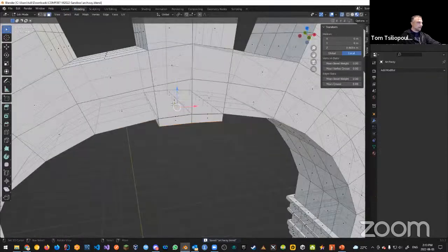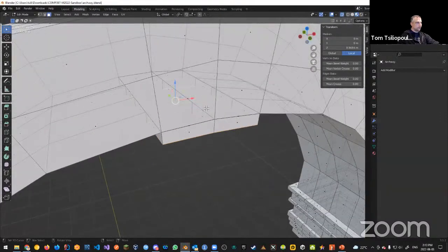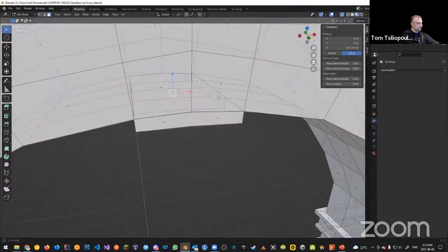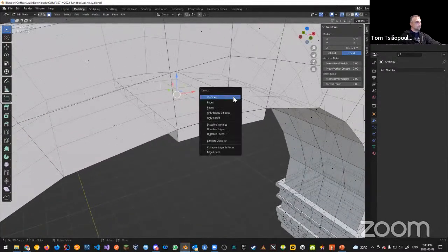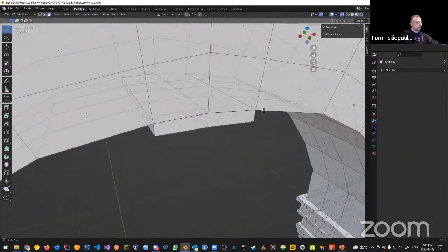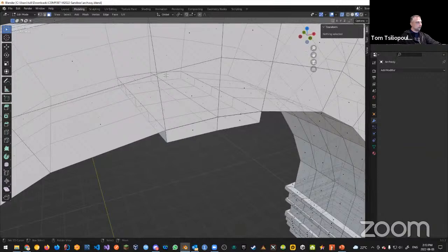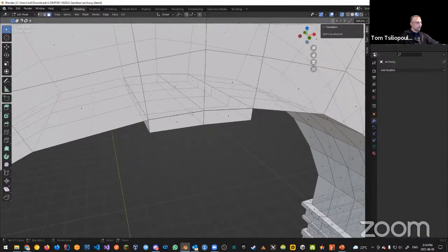I want to go back to modeling, and now we have access to every part of the geometry, which is good. And I want to just target those middle faces that are inside the model, those ones. We're never going to see those faces, and I want to press X, and I want to delete the faces that are inside there. But if I did that, then you're also going to have this additional edge, which is inside the model that you can't see, and I want to get rid of that too.